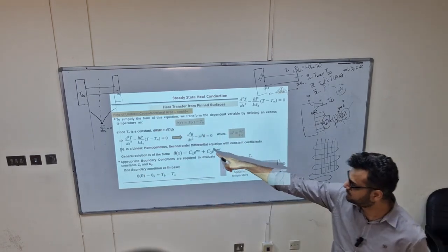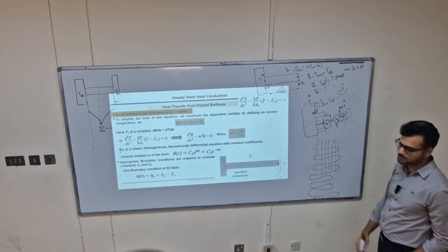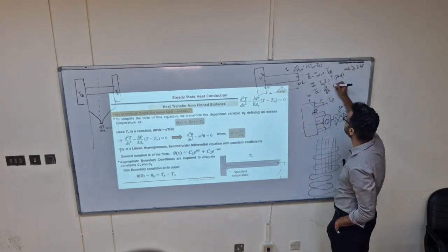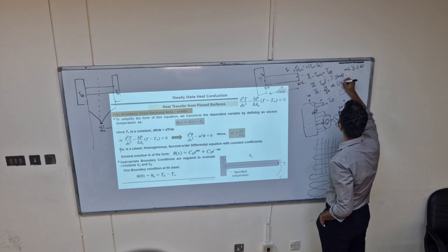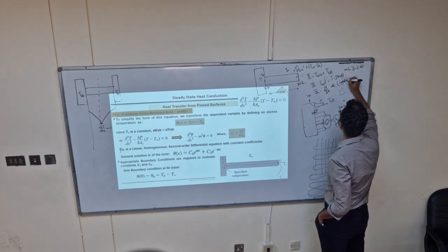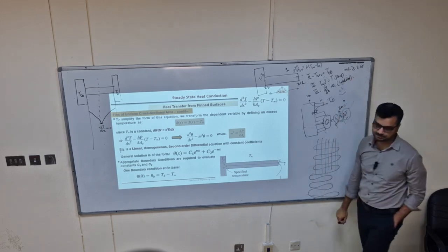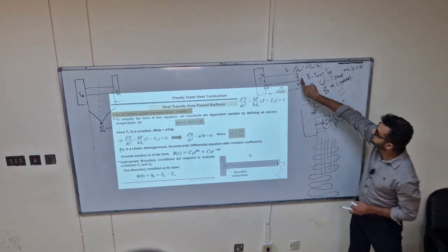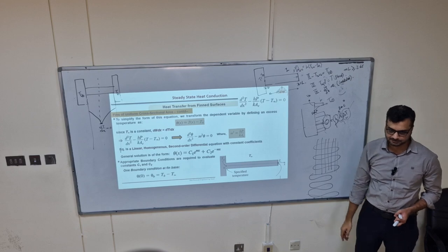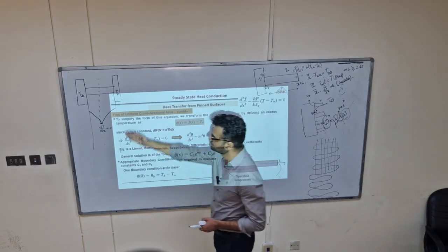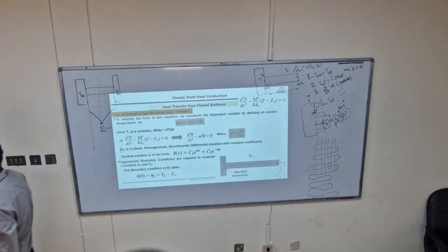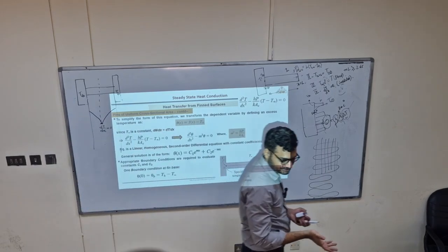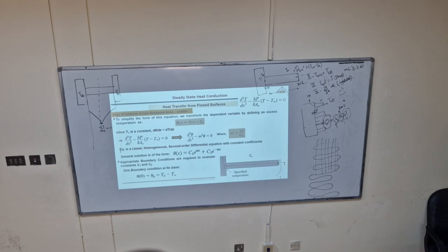Symmetry, but what is here in this case? dT/dx, or k dT/dx, is equal to 0. What is that condition? Insulated. At that point, at that tip. So this is one way where we can say the tip is insulated, because normally you never insulate the tip. Normally, we never insulate the tip.